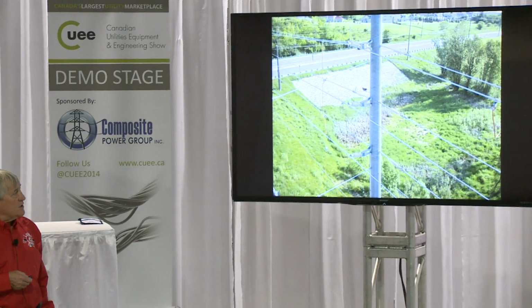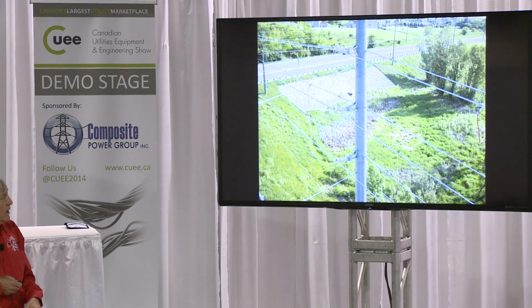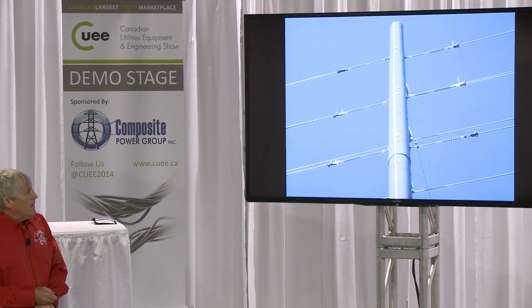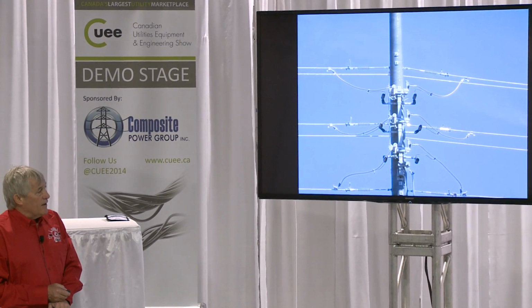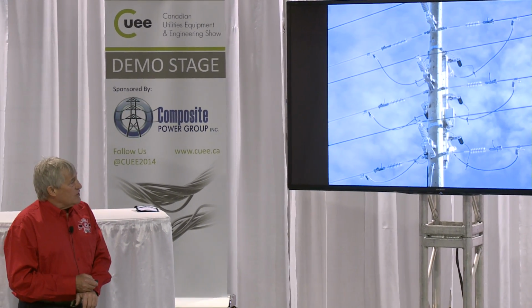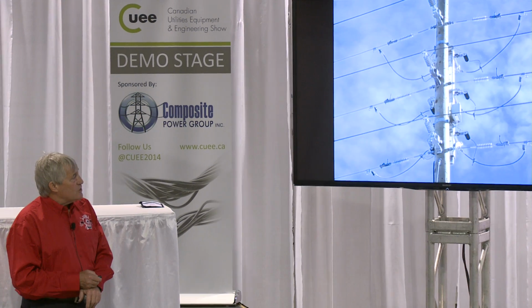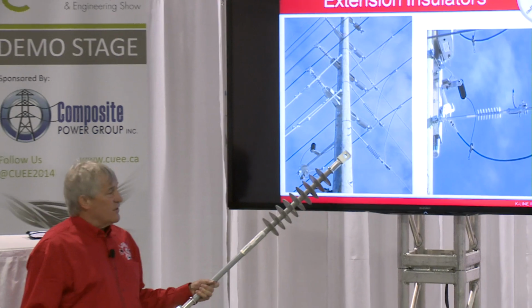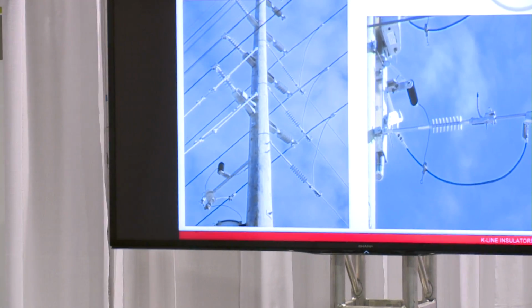The intent here is to put a switch on this double circuit pole, load interrupter switch. So there's the dead ending done on each side, completed, and there it is with the switch in position. Typical sort of applications, whether it's a load interrupter switch, you'll see oftentimes now if you're doing a single phase, or in this case it's a 3-phase tap off like to an adjacent circuit, and you can use, in place of that metal extension strap, there is now a purpose specialty product that will do it.